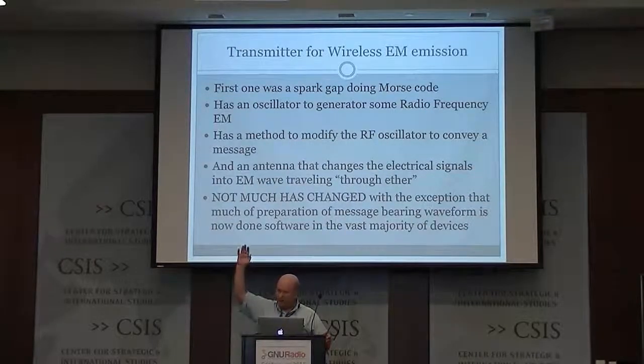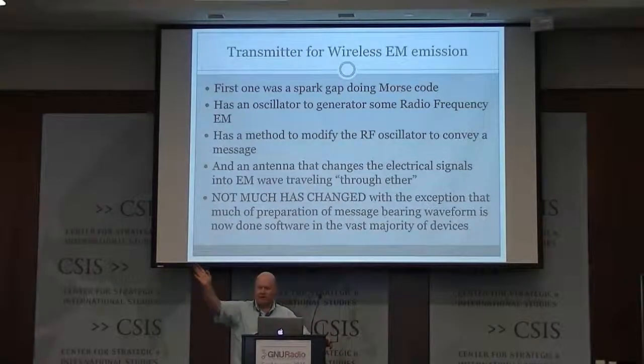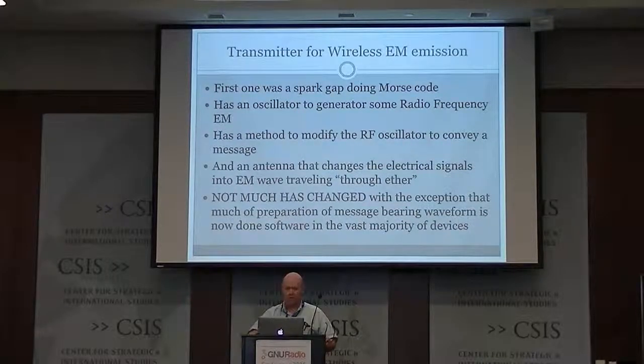I squared R. So if I am radiating, it's an effective resistance, because some of the power leaves the antenna and goes off into the ether. That's called the radiation resistance of an antenna. I have current going through the wire or the pipe or whatever's in the antenna, and however much it emanates is like a resistor, because it's dissipating power to the ether and beyond, and that resistance is called radiation resistance.